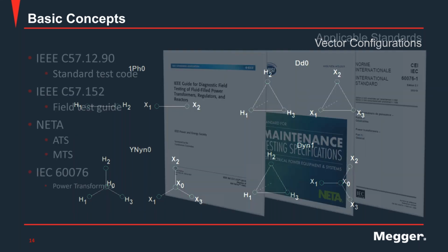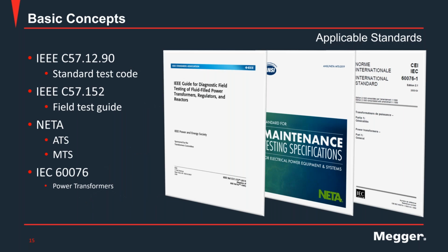I also mentioned that we need to compare these values to our nameplate and then determine if my measurements are within the limits. What are those limits? The IEEE dictates plus minus 0.5% of error when compared to my calculated value from the nameplate, my transformer nameplate ratio.